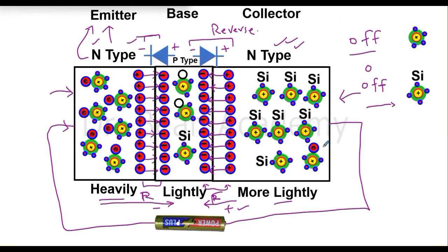So this setup is very basic, and we are actually not using it like a transistor, because now we have three regions, N, P and N, but we are only connecting two regions with the battery terminals, and the middle part, the P type or the base, is not connected with any voltage source or power source. So we are not using it in a proper way. In the next part we will see how we can do that.